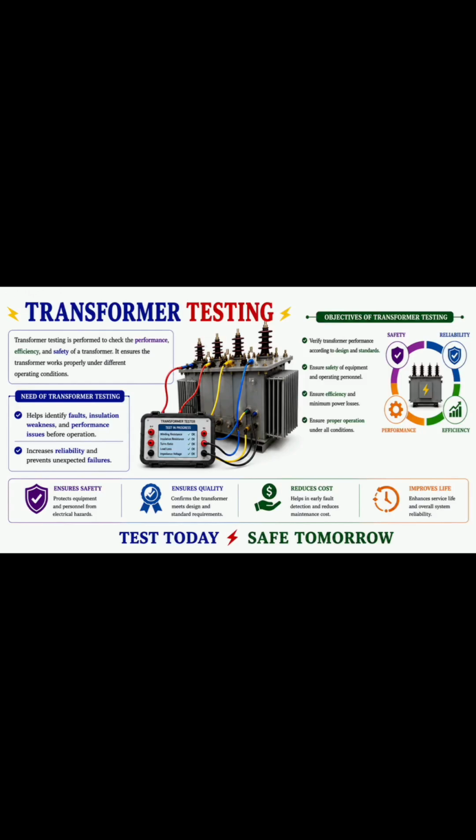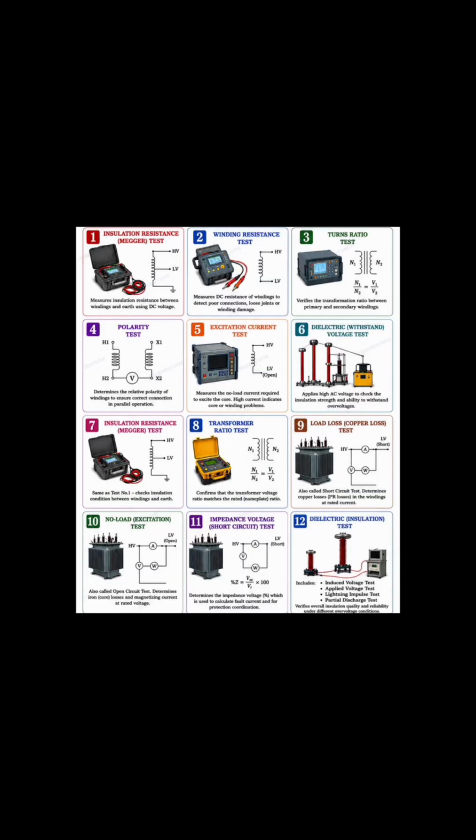Today let's discuss transformer testing and their types. Transformer testing is carried out to verify the performance, reliability, insulation condition, efficiency, and safety of a transformer before commissioning and during maintenance. These tests help to detect faults such as insulation failure, winding damage, short circuits, overheating, and poor connections. Let's see 12 types of transformer tests one by one.